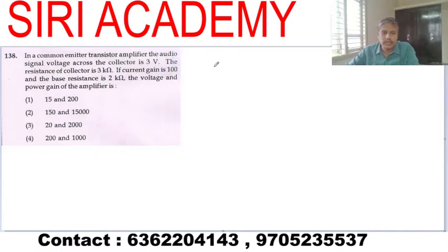So the voltage gain AV is given by beta times RC by RB. So that is equal to, the beta value is given to be 100, and the RC value is given to be 3 kilo ohm, 3 into 10 to the power 3, and the RB value is given to be 2 kilo ohm, that is 2 into 10 to the power 3.